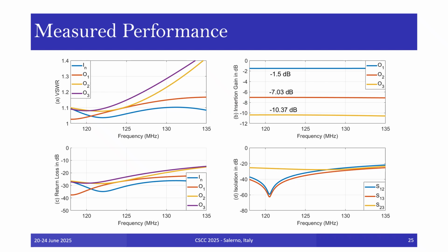The finite quality factor of the reactive components and their parasitic components explain the variation in the results obtained for the actual implementation. Nonetheless, the performance attained is adequate for the given application, even though further optimization is required to improve the isolation between ports 2 and 3, which is related to the proximity of the networks connected to these ports.